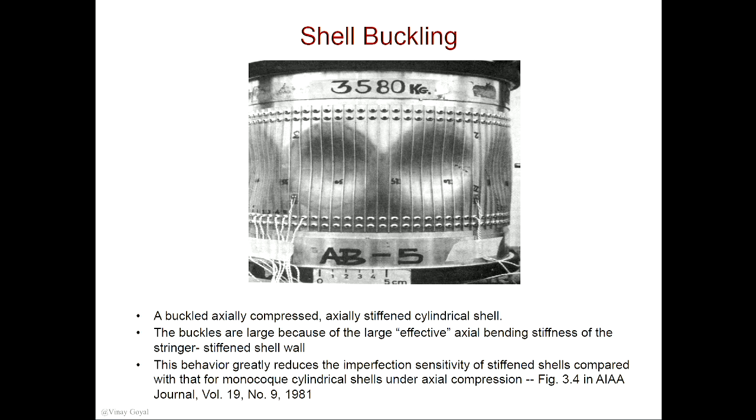But this wall is also stiffened, so it helps to prevent the buckling behavior. In that video you saw from NASA, it's an orthogrid. They talked about that. Those buckling shapes will be different from the ones you will see here, as an example. But stiffening the shell is one way to prevent buckling. Not only can thickening the wall help increase buckling capability, but adding stiffeners can help increase the buckling load, I meant.